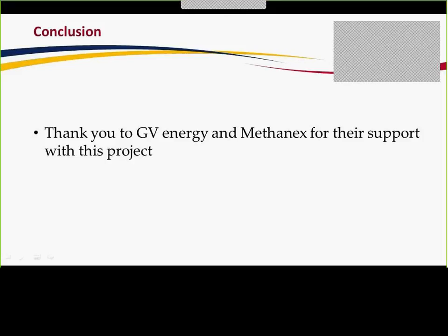Yeah, sure. The only other thing I will add on to that is Chemicon had a bit of issue with being okay with some of the sizes that we were recommending, especially for our heat exchangers, simply because a lot of the factors that it was using were based off of much larger equipment than what we wanted to design. So what that meant was the estimates that we're getting were being extrapolated as opposed to being on the curves that Chemicon was using, which meant that it's entirely possible that if we were to get an actual vendor quote for some of the shell and tube heat exchangers we wanted, they would be significantly less expensive than what Chemicon is telling us.